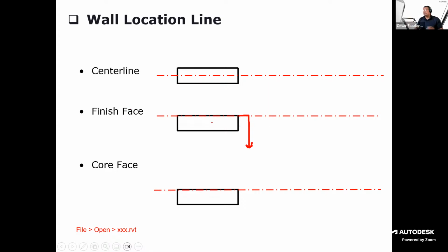is the plane that's going to anchor the wall to the ground. And so on constrained sites, you may want to use the finish face. Another place where you want to use the finish face is around elevators. You may want to wait for the structural engineer to tell you the final thickness of that elevator shaft.